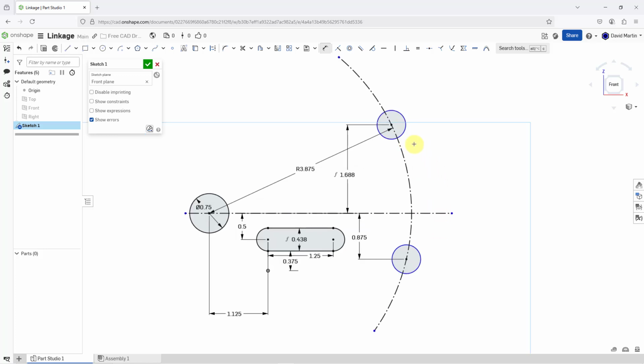And then to make the rest of this slot, I am going to put in a couple of arcs. And by the way, I've never checked to see if that's a default shape that's available in here, but that's okay. I can construct it manually. Let's create a center point arc again, and we'll center it on this circle. And I'm going to let it snap into being tangent here. Is it tangent? There. And let's do the same thing here, and then I'm not sure I'm getting tangency, but I can always throw that in later on.